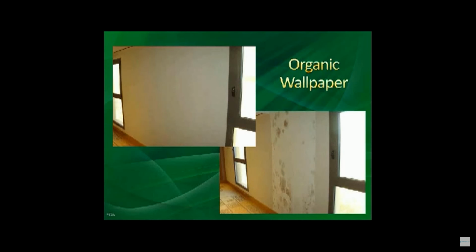This was an inspection in a hotel, a 25-floor hotel that had mold counts beyond belief. They tested the exterior walls, and all the walls came up very high for moisture, and I told them to pull off the wallpaper, and when they did, as you see below, there was mold behind it. We call this the "now you don't see it, now you do."